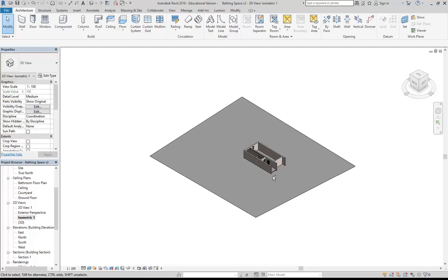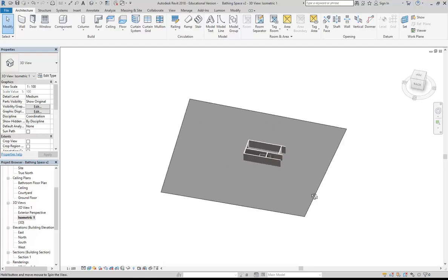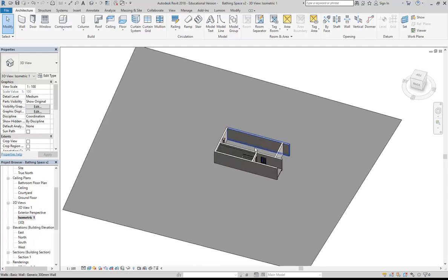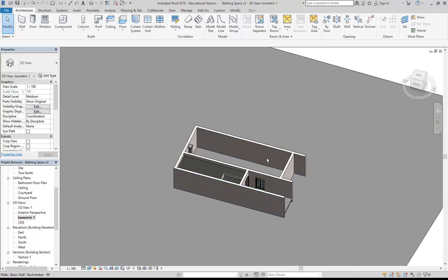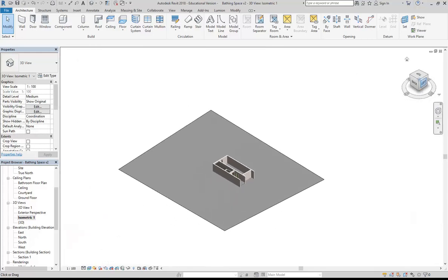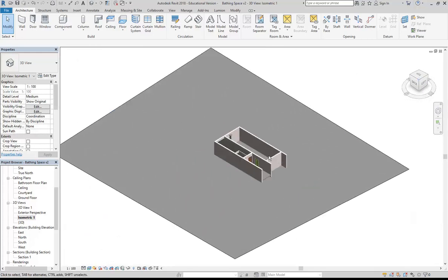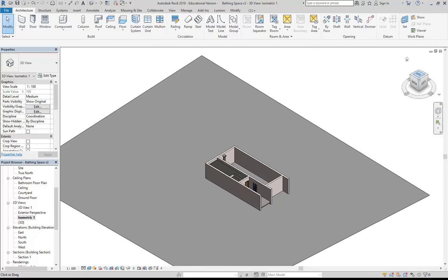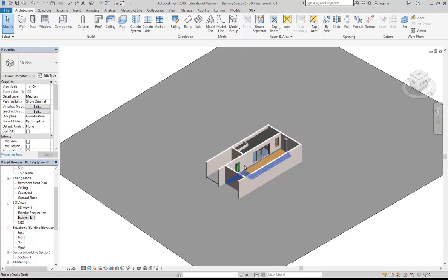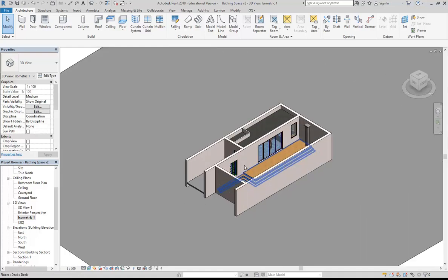If you change the angle by orbiting, then it's a similar view. Basically, that's an axonometric. An axonometric just means a view with a vertical axis. So all of those walls have vertical edges. But again, the angles now inside that cube aren't equal. So that's an axonometric, but again, isometric is just the one with the equal angles. So they're really useful views for clients. Clients sometimes prefer these to perspectives even, especially if they have trouble reading a floor plan.